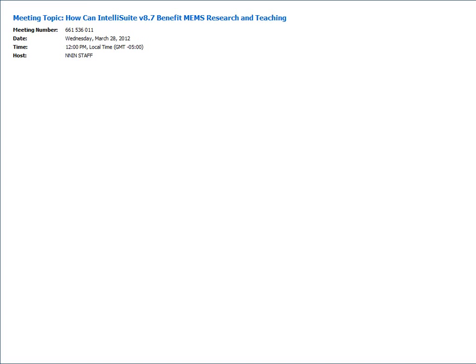And you can initially explore your design that way. From there, you can export the mask layout that you're going to be using. You can automatically generate the 3D model, and from there you can do some further analysis. Maybe look at the different resonant modes of the accelerometer. Look at exactly the accelerometer behavior and how it's going to behave under different conditions.